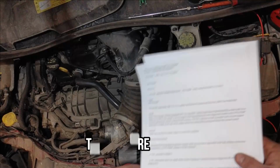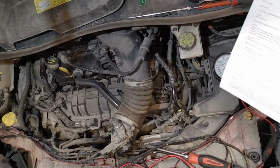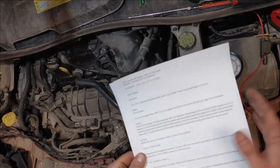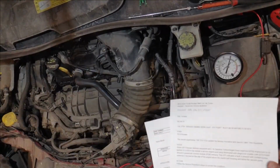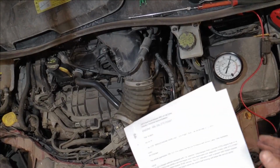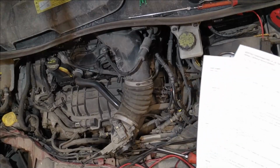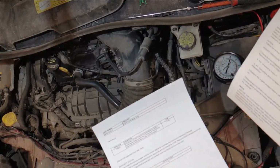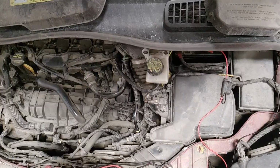So yeah, that's it for this diagnosis. There's not very much more that I could do. I do need a purge valve, and I'm going to end up needing a coolant bypass solenoid C, which they say is located on the back of the engine above the vacuum pump. So we'll see where the starter is on this, because they say it's located around there, and they say it takes 1.7 hours. So we're going to see what's going to be done with this one.